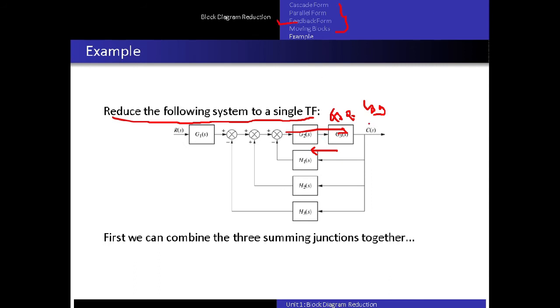Whenever there is a forward direction element, feedback will be there. In that case it will create a loop, and for that you have to remember the transfer function can be found out by, here you can see that the sign is negative, it means the negative feedback system. It means the transfer function can be written as G divided by 1 plus G into H. If the negative feedback system is there, the sign here will be positive.